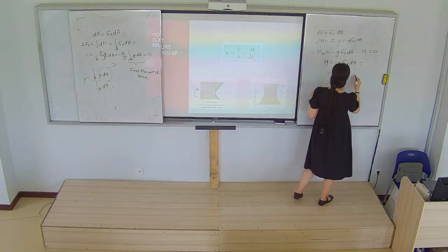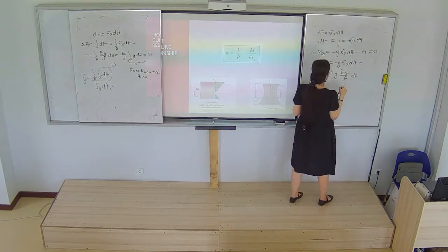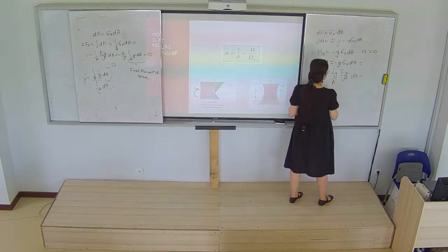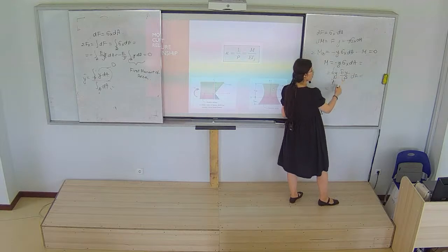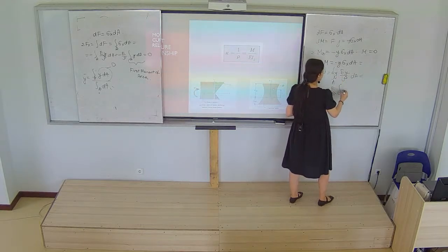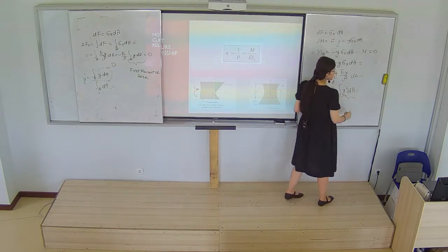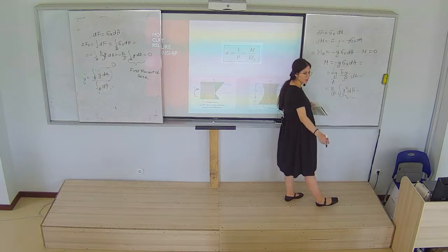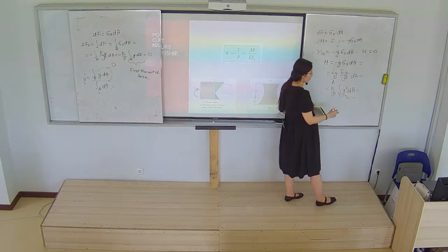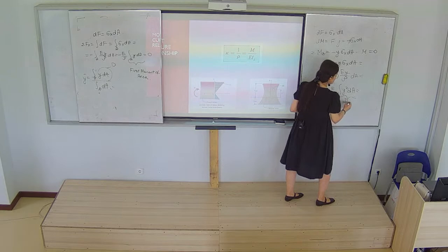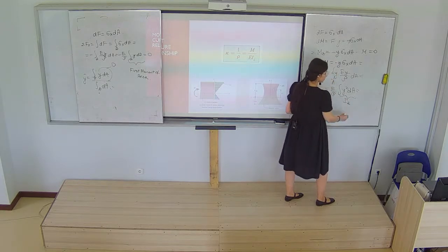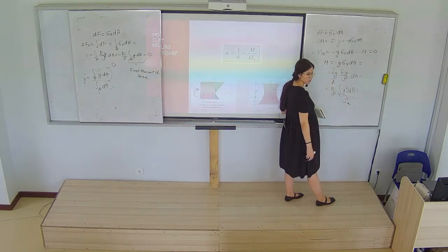So, dA. As we have a dA, we will use the integral form. E and rho are constants, so I will take them out. And we will have the integral of y squared dA. It gives us the second moment of inertia. Last time I called it J, right? Right now I will write it as the inertia in the z direction, Iz. Do you understand this one?